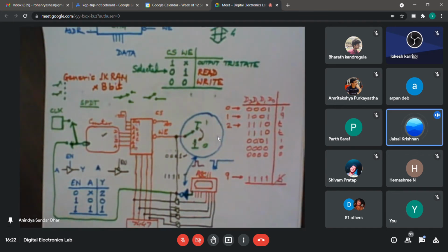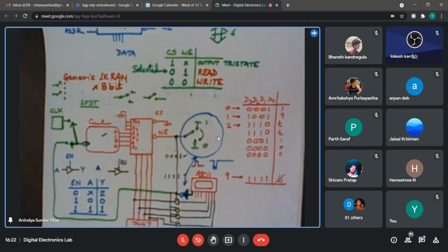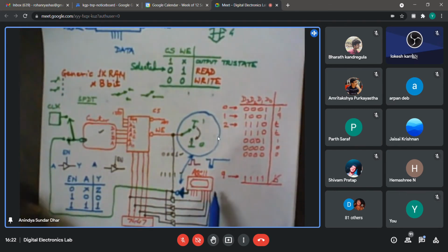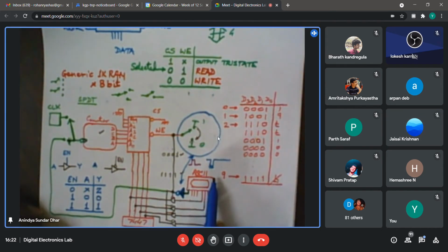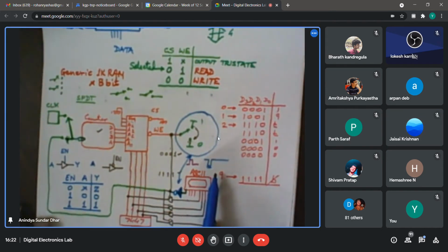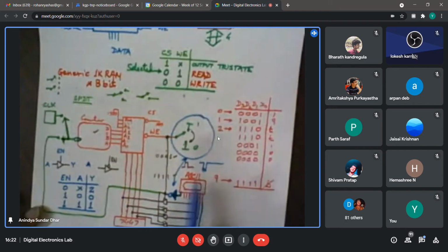Also, one more thing: why did we extend the length of the clock signal initially? Can you just tell that once again? It is actually because of a problem of the simulator. In that simulator, everything is coherent. Coherent means it is dividing the clock's pulse into 10 time units called ticks. And some signals, for example this strobe signal, remain high only for one tick, that is 1/10 of the clock's period.